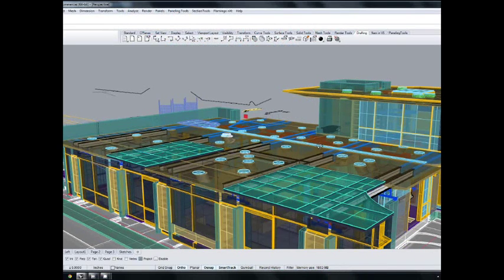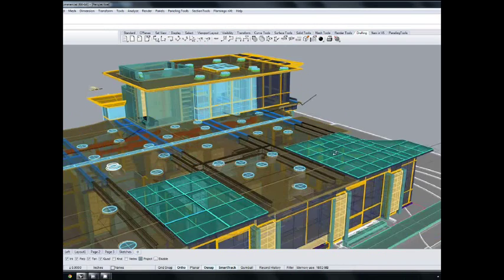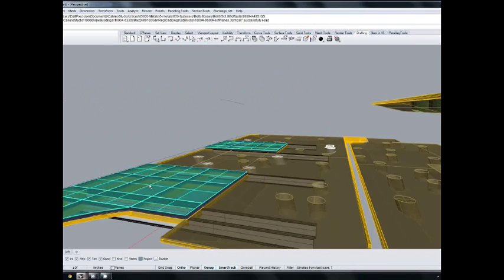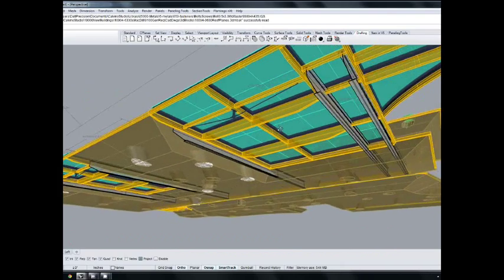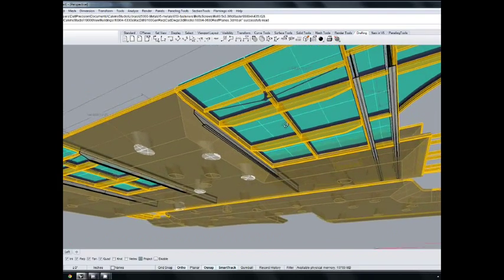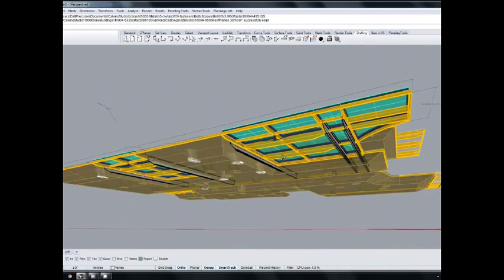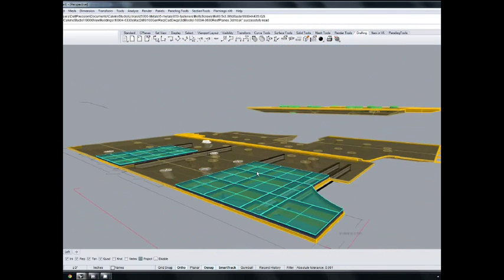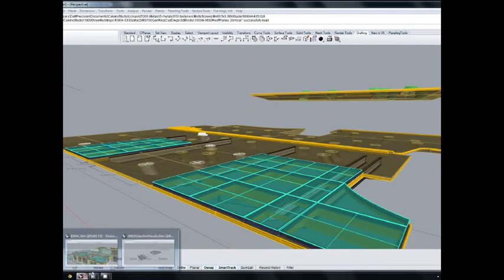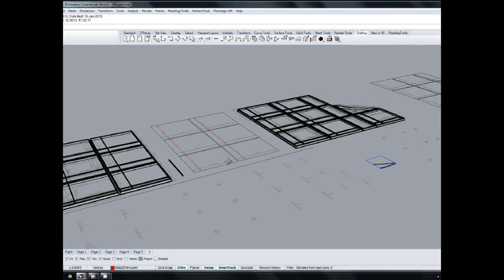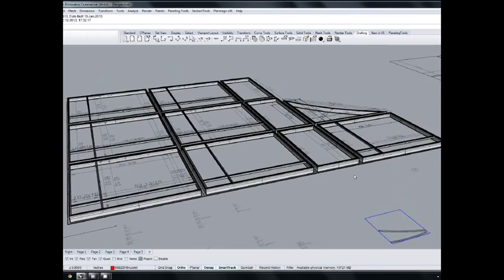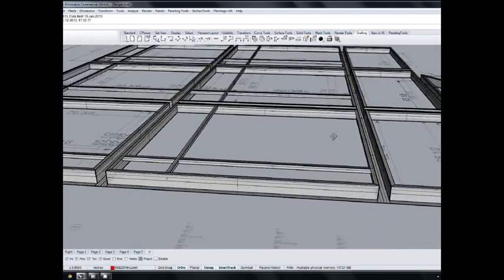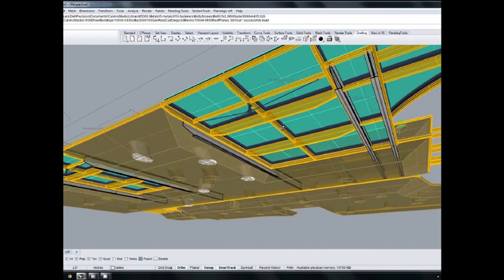With that as the basis also, we can do overhead glass systems because we've broken it down now into a set of load conditions, defined the set of load conditions, and then designed the members that support it based on those loads. So now it doesn't matter if we're using steel, like these frames here, or a combination of steel and cypress. And in this case, there's one condition at the edge that has a steel tensile rib underneath it.